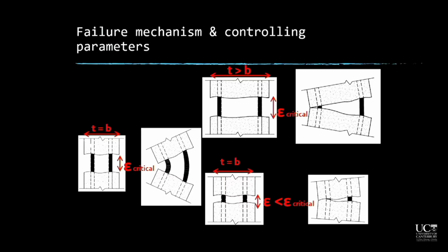So the parameters that are governing this mode of failure are first the wall thickness, or let's say slenderness ratio. What I mean by slenderness ratio is the unsupported height to thickness, because as you know, the unsupported height is also a key parameter. But since the unsupported height of walls or the story level is sort of constant in structures, we are dealing with thickness, and thickness is considered as the variant in our analysis.